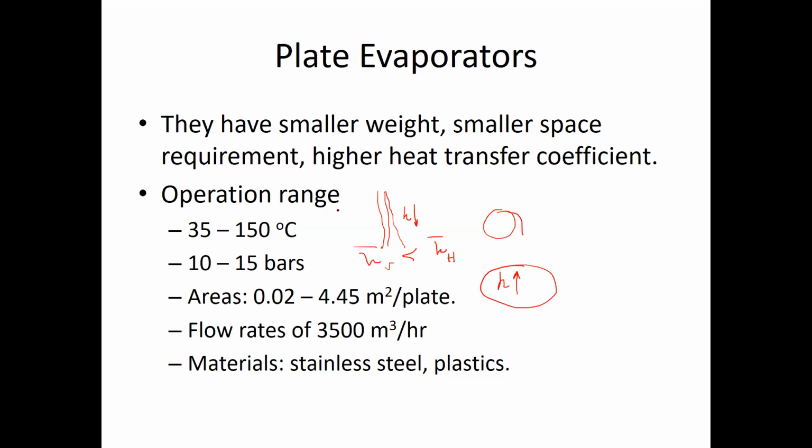Excuse me? I mean, we have two boundaries, a boundary for velocity and a boundary for the temperature, isn't it? Yes, I'm talking about the temperature boundary layer. In the temperature boundary layer, this is the distance from the temperature as it changes from the surface temperature of the tube to 99% of the bulk temperature of the fluid which is being flown in here.